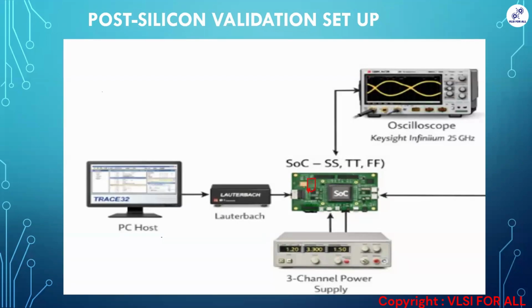Any differential high speed protocol has the same signals, TXP, TXN, meaning transmit positive, transmit negative, RX positive, RX negative. We will take those 4 signals and probe them to the oscilloscope. For example, this port is for SGMII. This port will be for Aurora on the validation board.